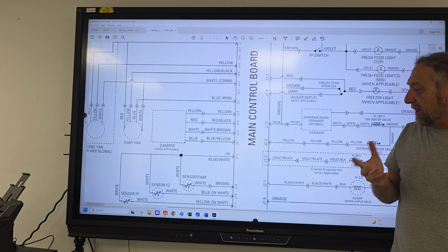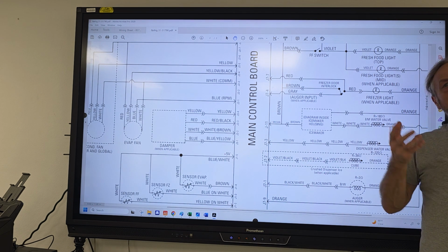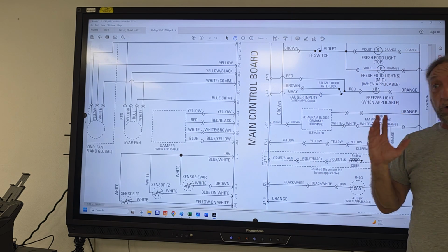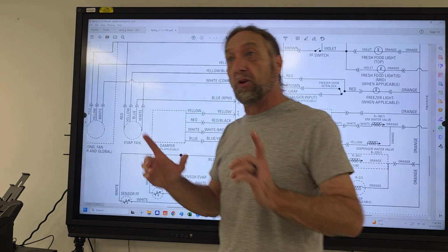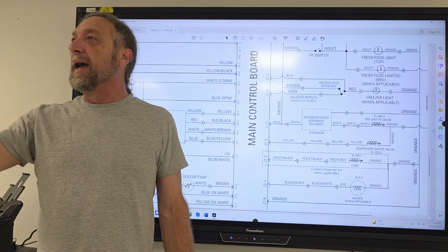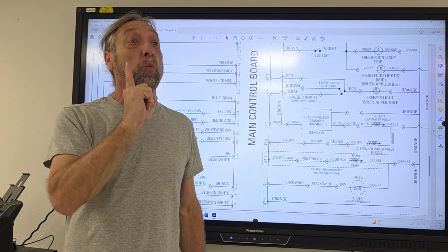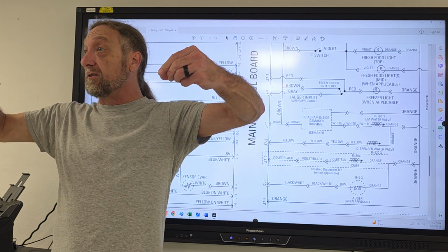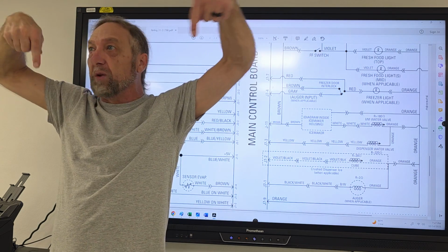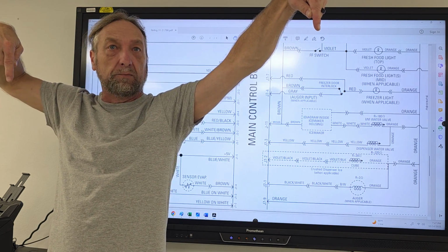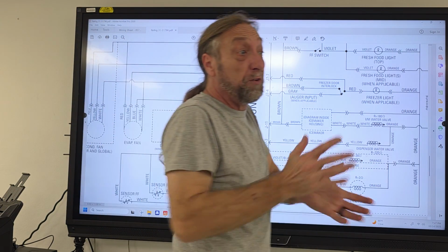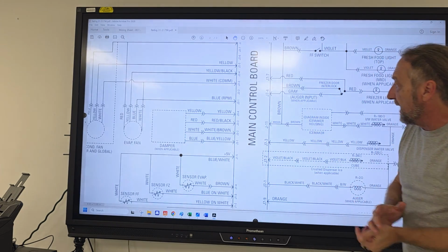Okay? Now you're like, well, when I look at the plug, how do I know which one is pin number 1? Well, a lot of times on the actual board, and I want you guys when you're working on the machines to look at the computer board and see the connectors on the board and see if you can find a marking number 1 on all those connectors. Once you know which is pin 1, then you know the rest are 2, 3, 4, 5, 6, 7, 8 after that. If you don't know which is pin 1, because sometimes the number 1 is not printed on the board, I could look at...